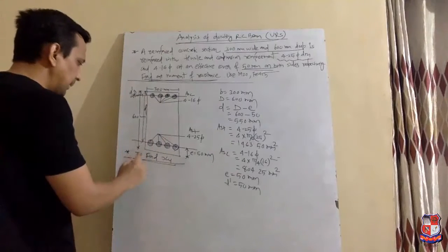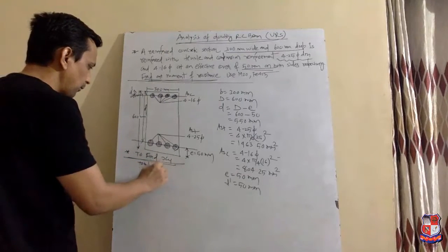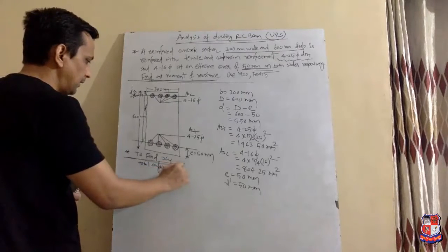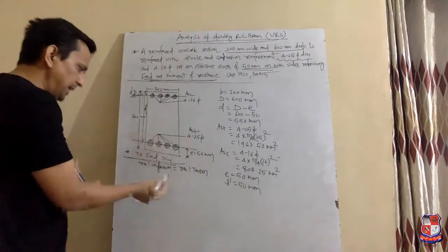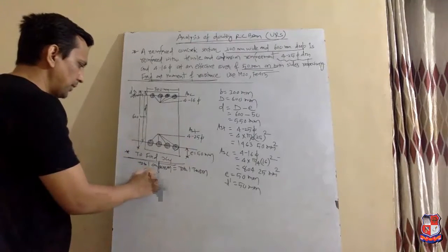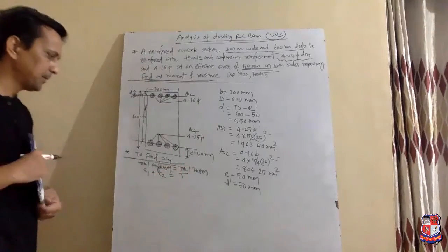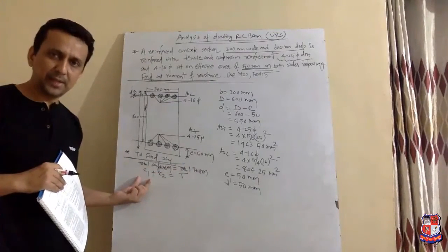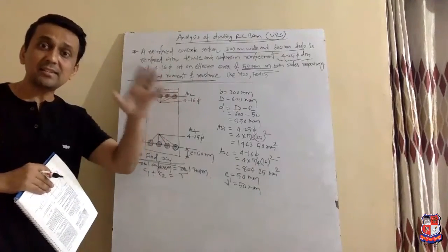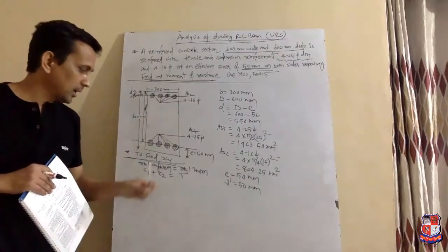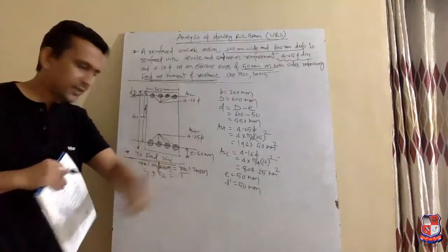So in WRC beam, total compression is equal to total tension. In WRC beam, total compression force is C1 plus C2 and the total tension is T. C1, I have already explained. C1 is the total compression force in singly RC balance section. And C2 is the total compression force in auxiliary section.